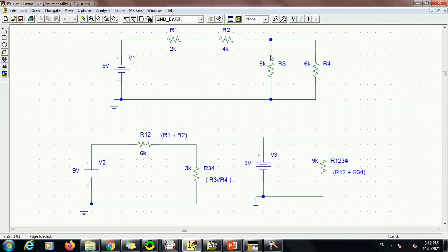If we think of our house, for example, where we see the electric sockets, for all the appliances that we are using, we need a constant voltage for the devices, whether it is 220 or 110. So this means that all the connections in the house are connected in parallel, so that this will ensure that we get the same voltage for all the appliances.